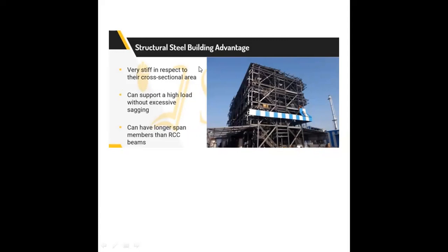Next, let's discuss the advantages of a structural steel building. Steel is very strong with respect to its cross-section area, can support a high load without excessive sagging, and can have longer span members than RCC.